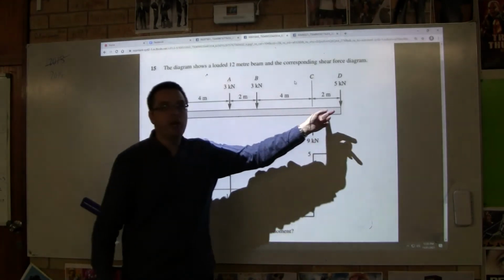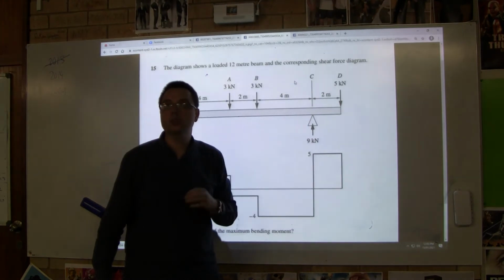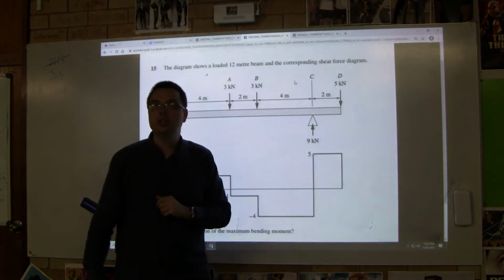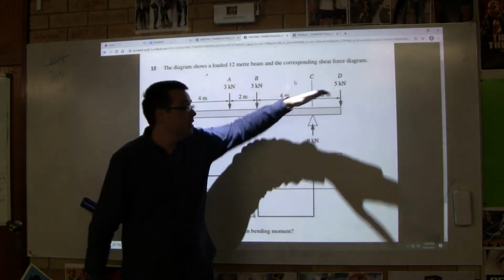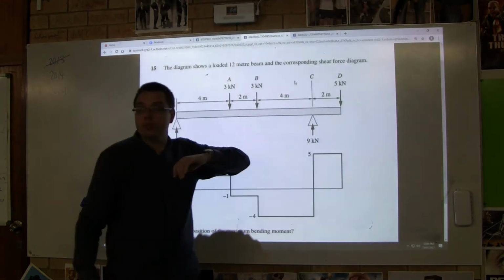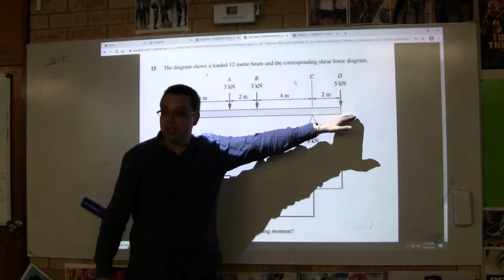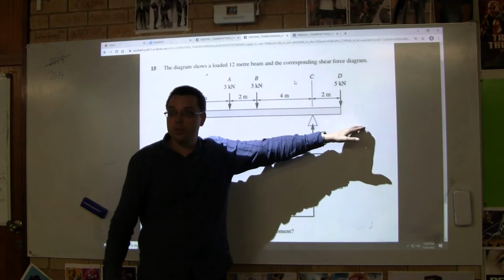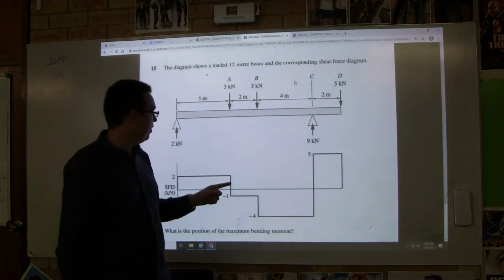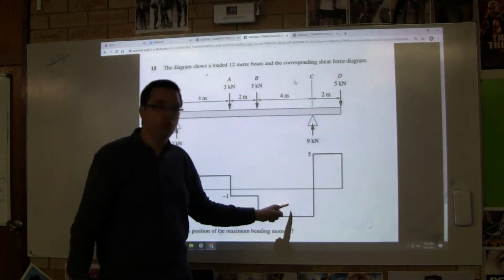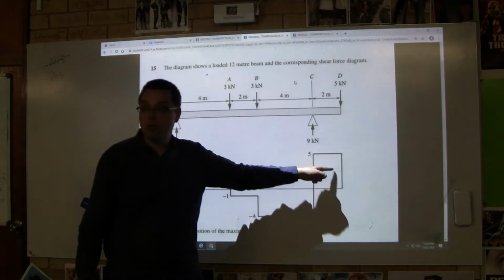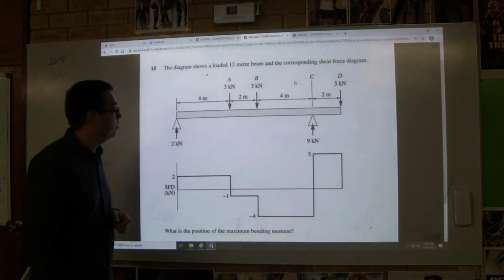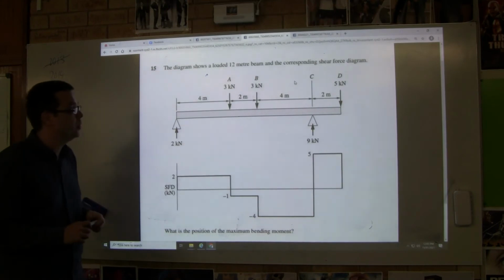What do we call this little part sticking out over the top here? Starts with a C? Cantilever. Right? Sticking out over the top, cantilever to extend past the reactions. Now, when we have a cantilever, do you see how that gives us this unusual graph? This part coming up here. We're going to see how that affects the bending moment diagram when we draw a bending moment diagram.